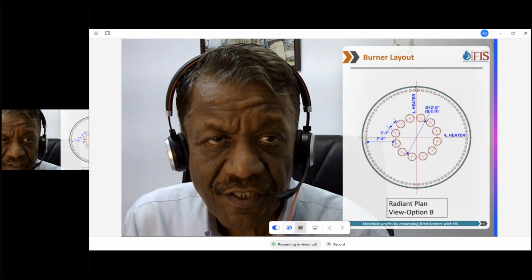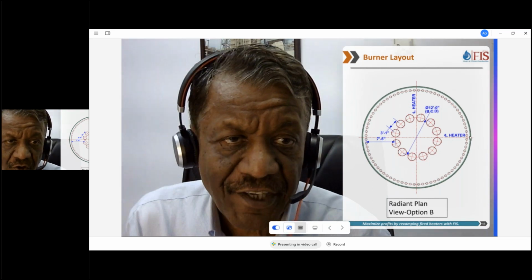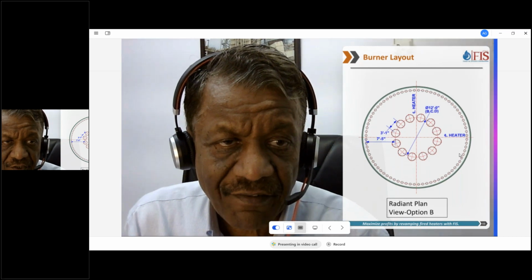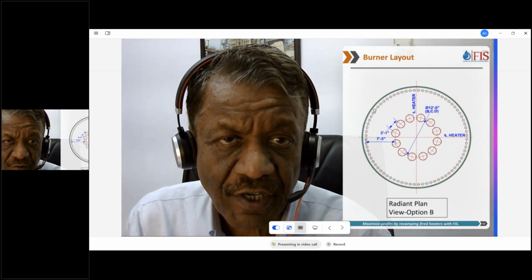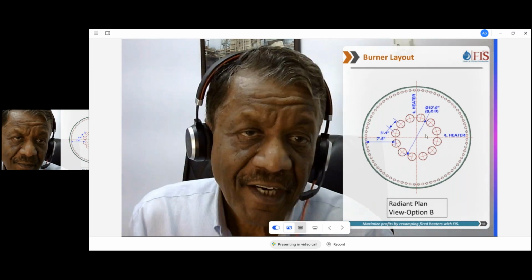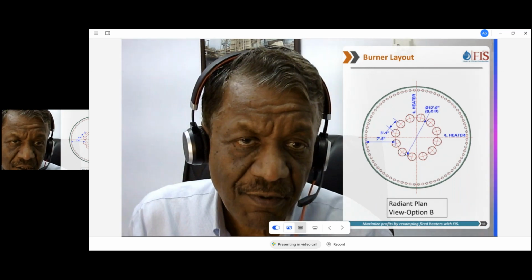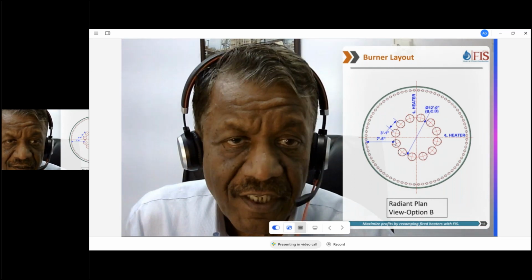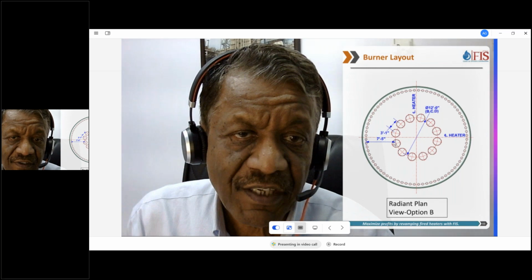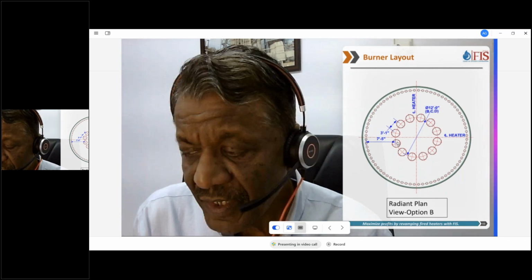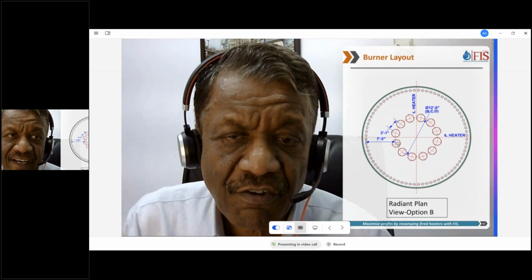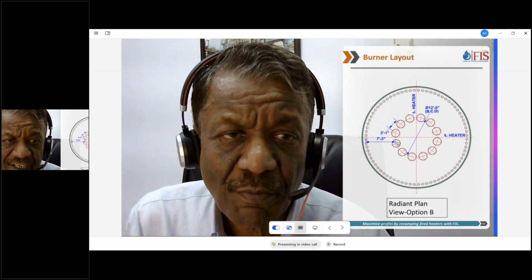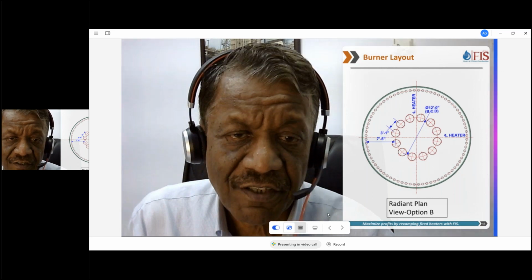This is the outer circumference of the heater, the wall. Then we have the refractory lining, and we have 84 tubes over here, and then 12 burners over here. We came up with a 12-foot burner circle diameter. The distance between burner to tube is 7 foot 5 inches. So we are very generous in terms of clearances. We give a very good, robust heater design for this service.